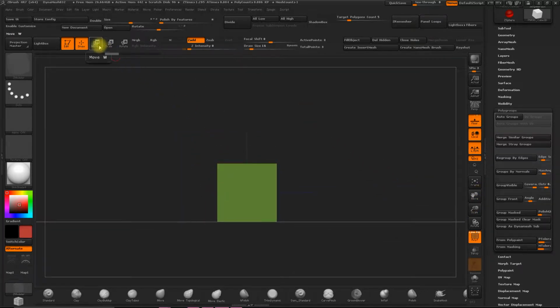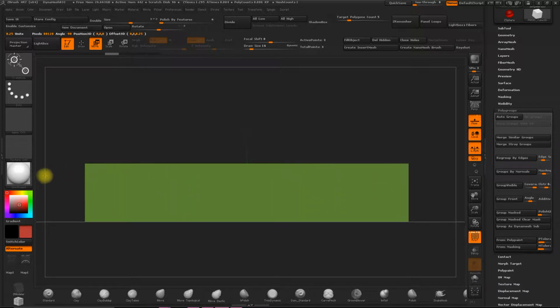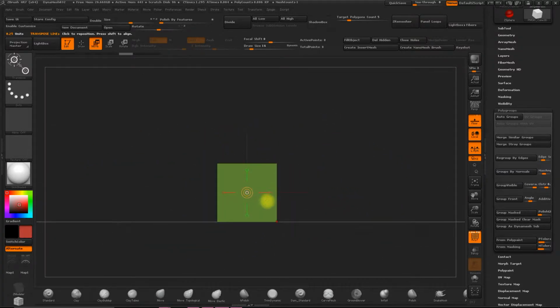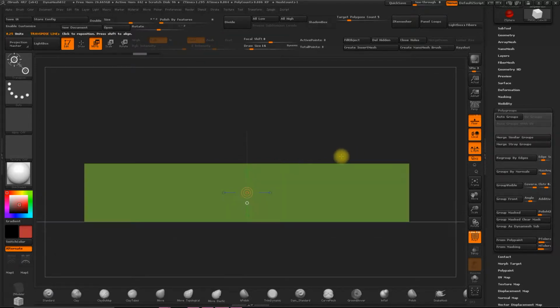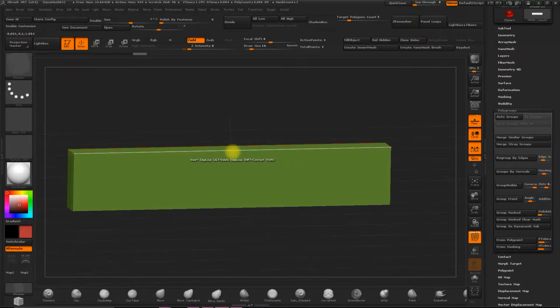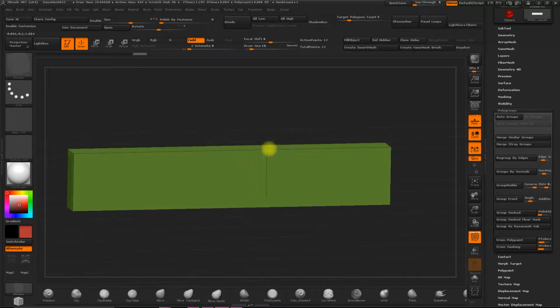We'll get this cube. We're going to move it. Activate move. And now we can stretch it from this point, holding the shift key. And we'll make a kind of extrusion, or we'll elongate it from the cube. We'll do it this way. We'll put it on this view, activate it with a click on the gizmo, and we'll make it a little bit thinner. Okay, now we'll make a cut. The cuts are made in the following way. Hitting right click on the edge and marking insert. This way we can click and put the cut wherever we want to place it.